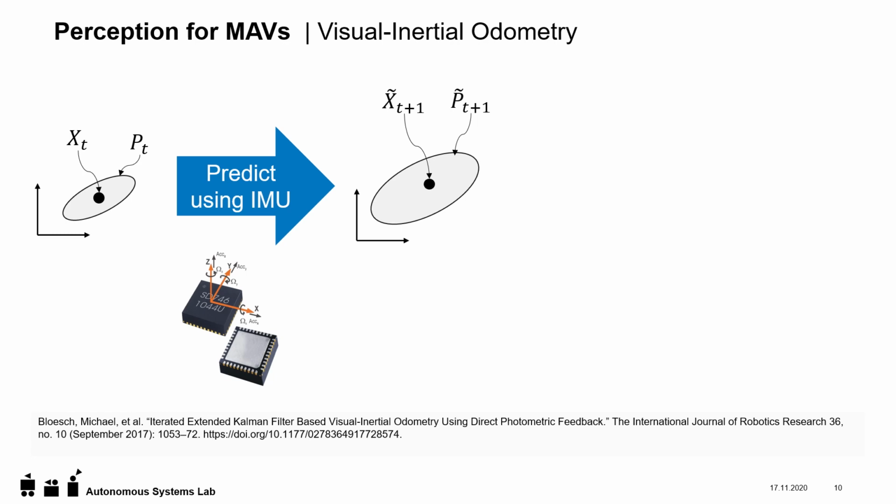If we would only update these steps and reiterate using the IMU, the covariance would grow unbounded. That means at some point we don't know anything about our state anymore, which also reflects a bit what actually happens if you forward predict using an IMU only.